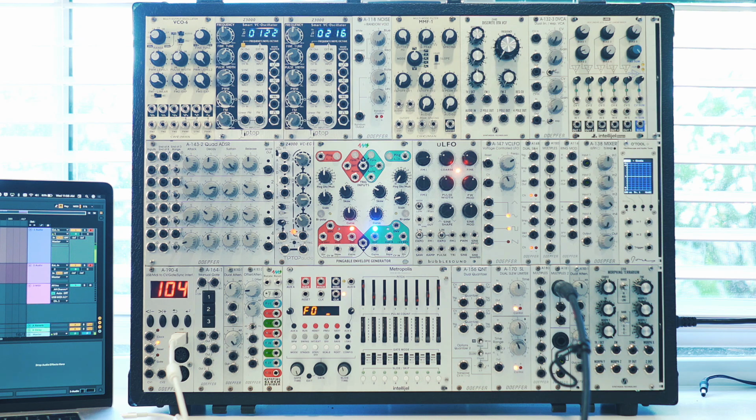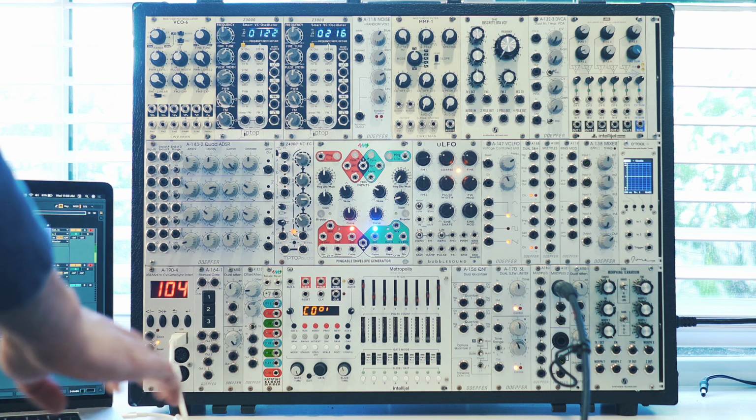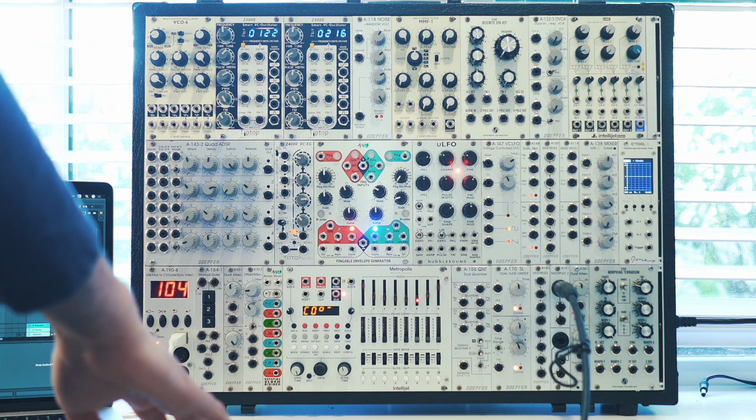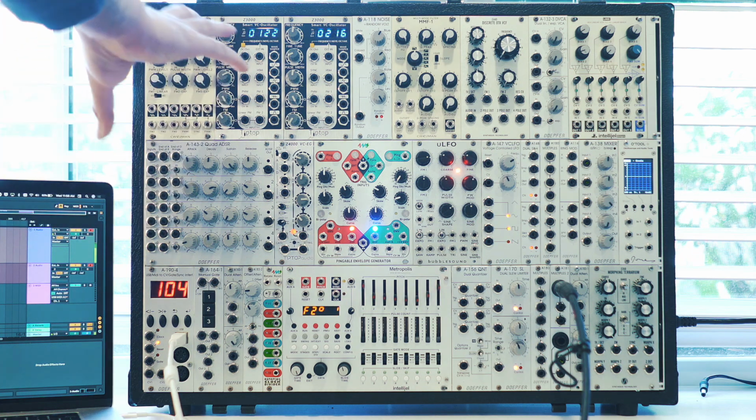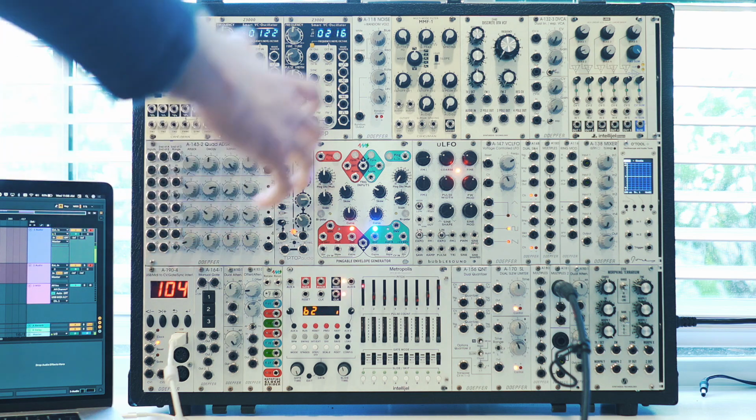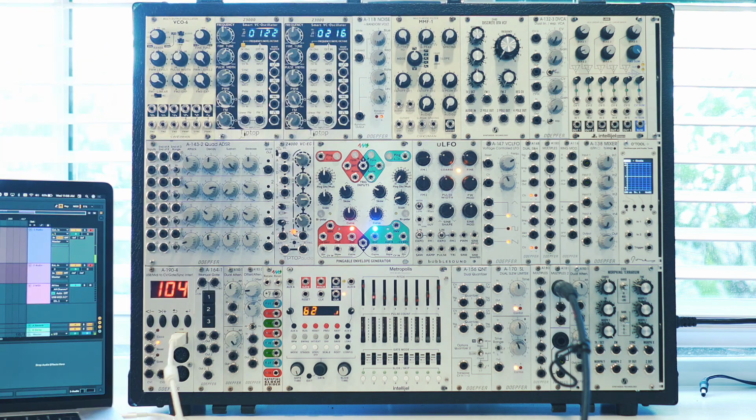In this video, I'm going to show you how to create a simple single oscillator voice patch using this Eurorack system. I have MIDI data coming out of Ableton Live on this computer here, going into this MIDI to CV converter module. So I'm going to use two pieces of information from the MIDI world, the pitch information and gate information. Pitch is going to be used to control the pitch of the oscillator, and the gate is going to be used to control the volume of the sound.